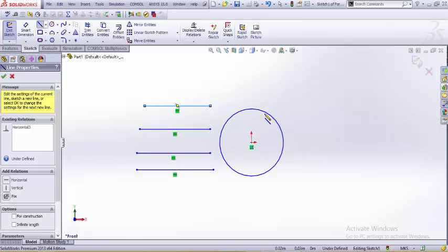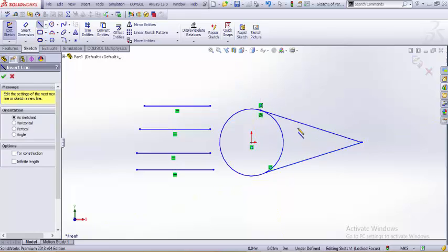But if we can make something that is tangent like this, this extra bit of area would reduce the tendency of the fluid to be separated, and this is called streamlining, and this reduces pressure drag by a huge amount,